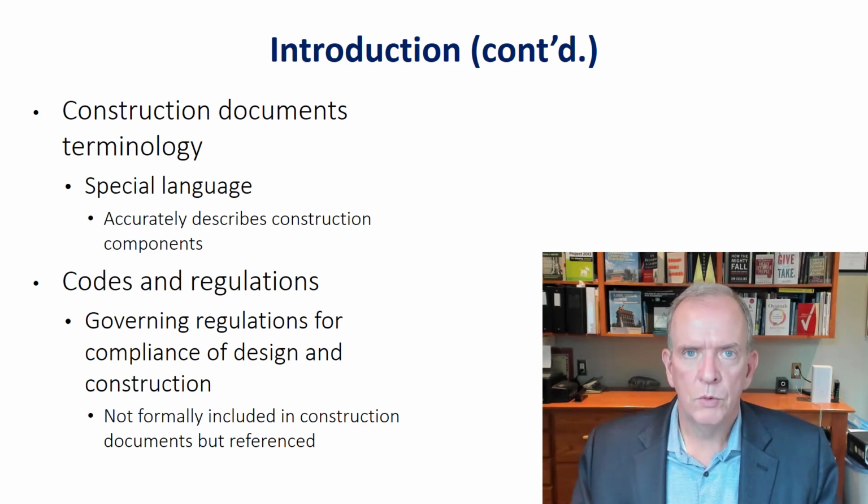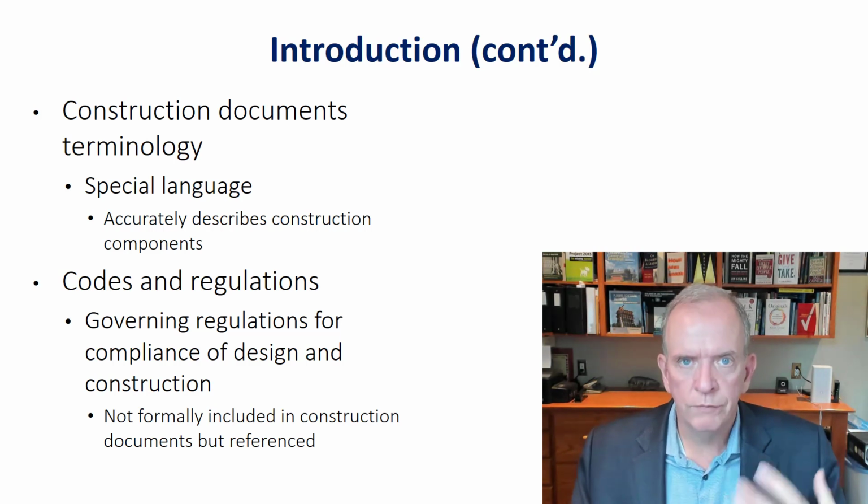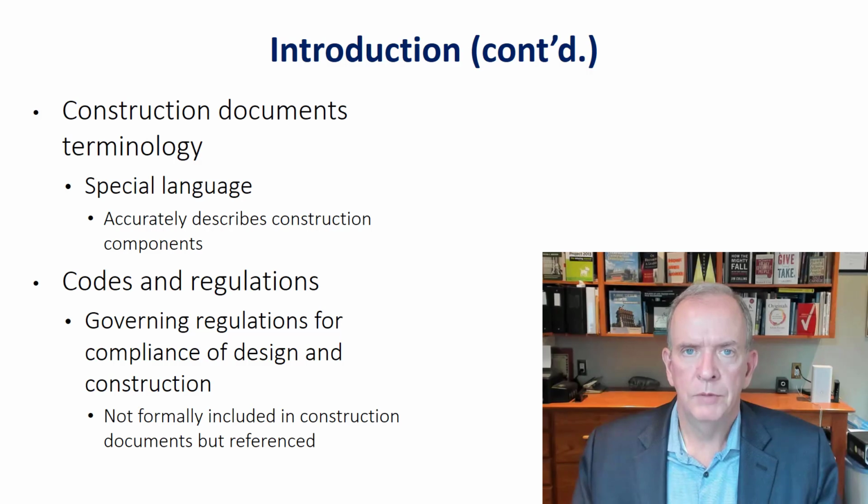And of course, we can always ask and get clarifications on some of the information that's provided, because there's always omissions, there's always errors, and there's always missing detail that you need to get clarifications from the designer. And we use what we call an RFI, request for information process, to gather that information. And that way it's also well documented.